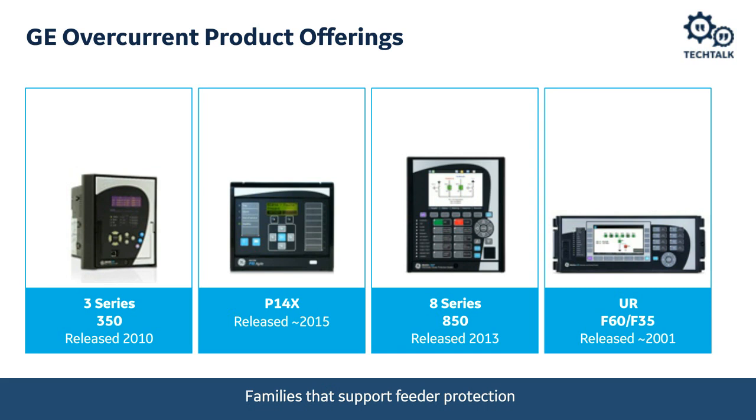As you can see, this relay has multiple push buttons, which give you the ability to control your equipment or control the relay from the relay itself. So you don't have to have discrete 01 for operating the breaker, or discrete 43 switches for choosing options in the relay. This relay also has a large graphical faceplate that helps you to operate as well and helps you to mimic the real world.